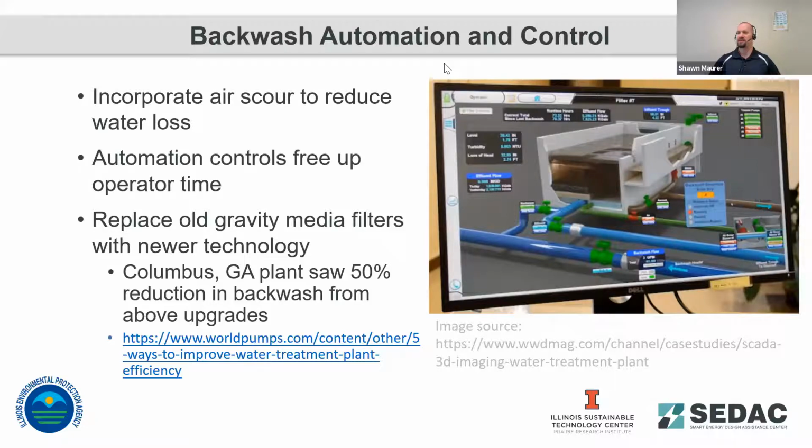That helps break up sand particles, buildup of materials in that sand bed. And then they'll also do an air scour as part of that in a staged process. So usually air scour happens, breaks up some of the materials on the surface, and then backwash water goes through the system, flushes out those broken up materials into the backwash line of the filtration system.